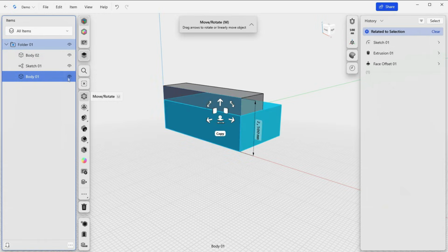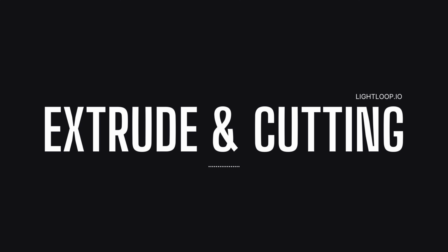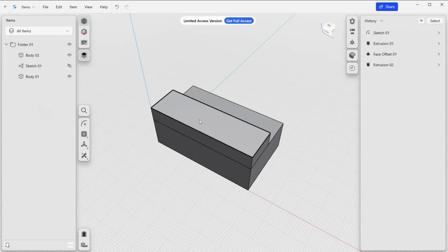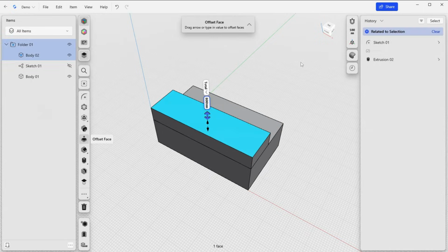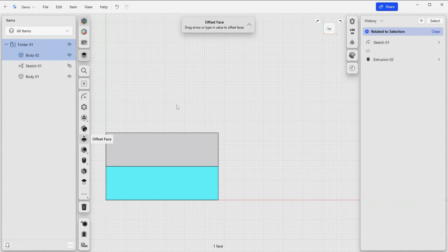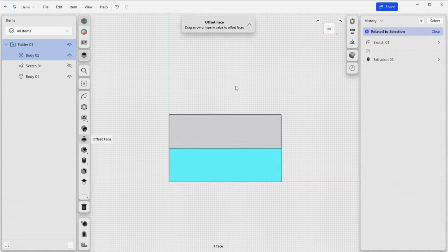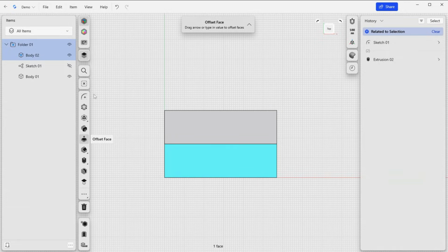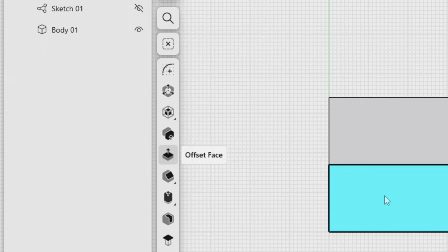Okay, so now let's imagine that we want to drill a hole through the top of this part of our object here. So let's select the top from the upper right corner here, and then we'll use Control or Command to reposition ourselves in the middle of the canvas here. Now let's select the top face here, and then what we'll do is we'll select Sketch.